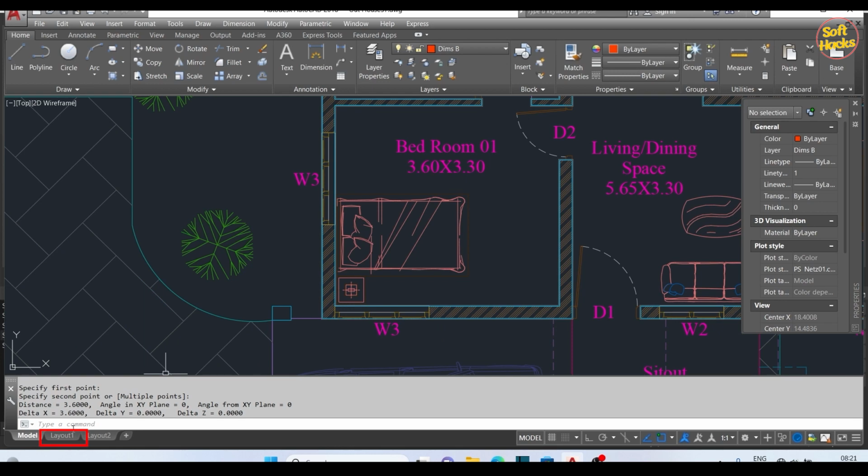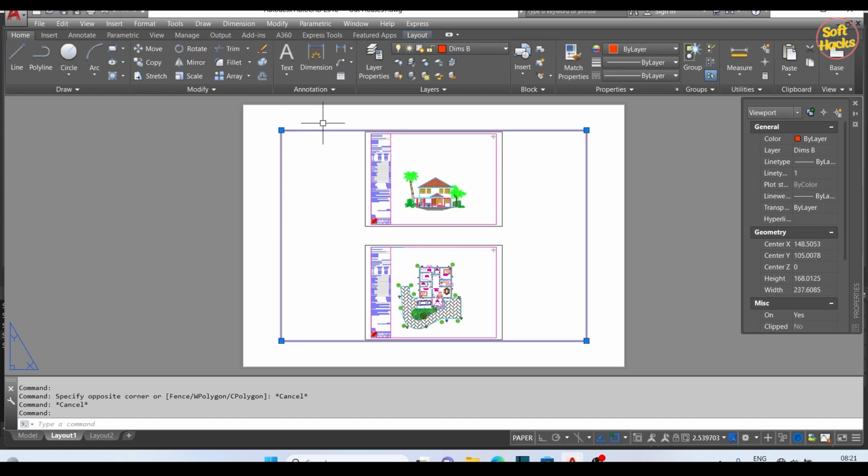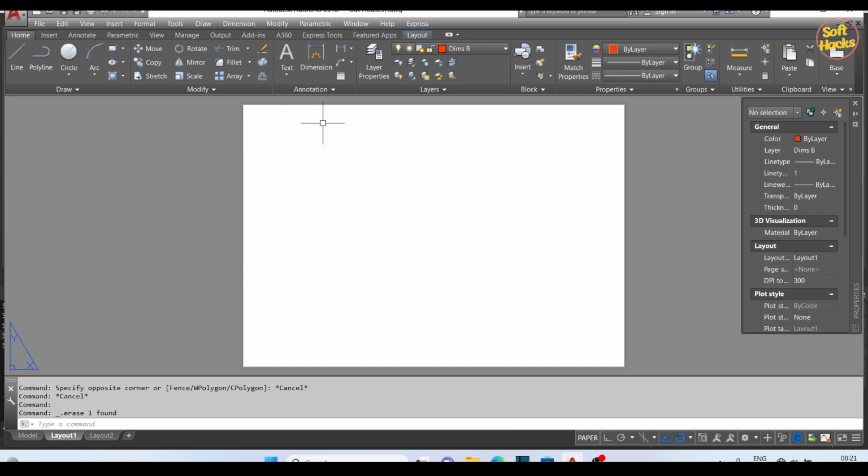Now let's click on this layout tab and we get this paper space with a viewport in it. This is the default viewport that we don't want anymore. So we click on it and we delete it. So this is the empty paper space that has not been scaled to any size by us. We have to make it represent a particular sheet type.